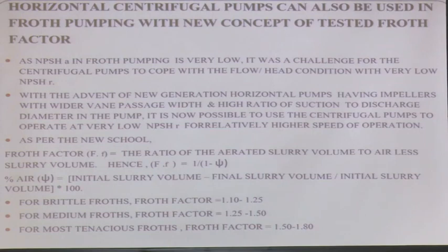Horizontal centrifugal pumps can also be used in froth pumping with the new concept of tested froth factor. What is tested froth factor? As NPSHA in froth pumping is very low, it was a challenge for centrifugal pumps to cope with the flow versus head condition with very low NPSHR, because it is already having froth. So, NPSHA is obviously low, and NPSHR has to be even lower than that.